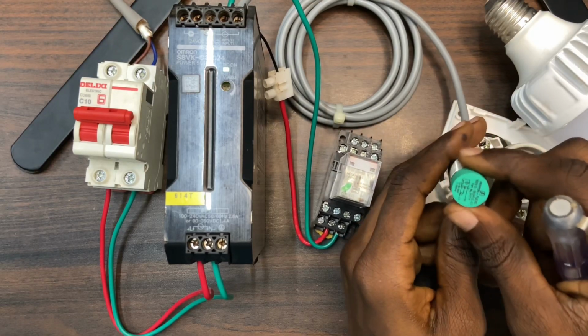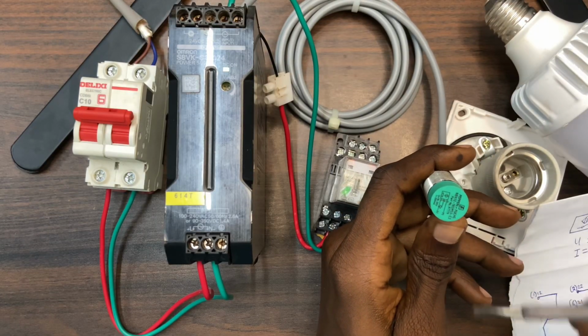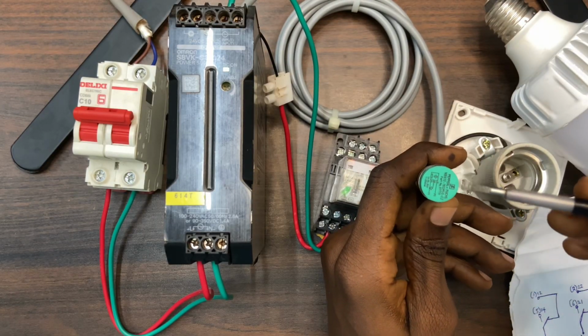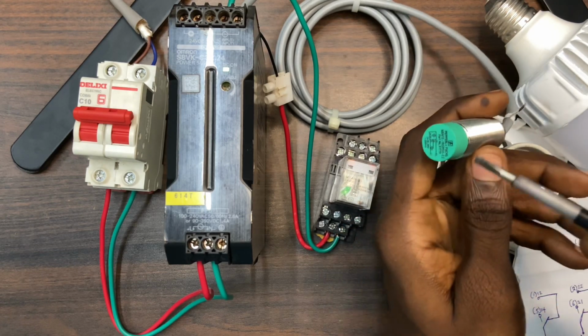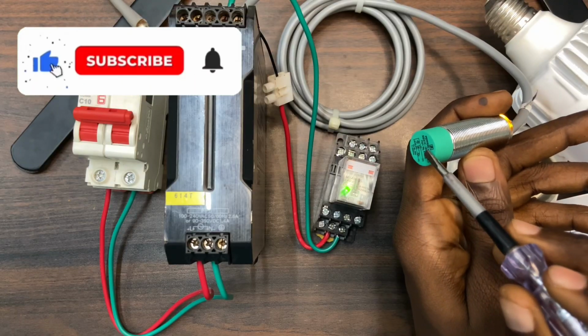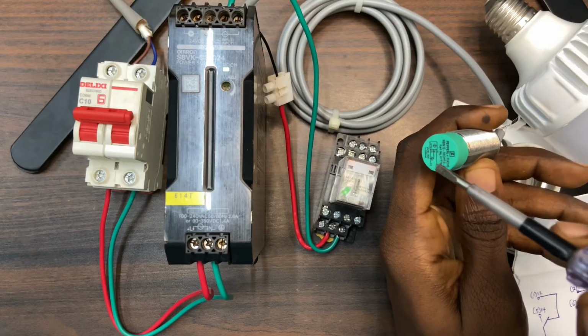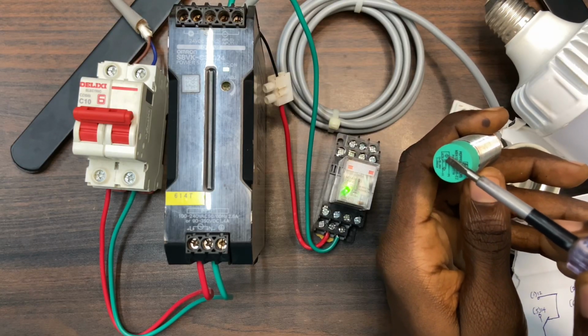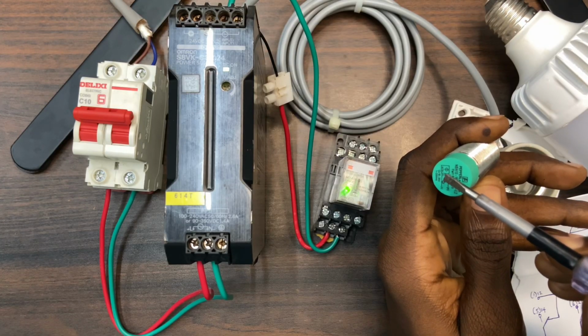And sometimes it depends on the sensing range. If the sensing range is very high, even if you bring the metal, something like this, it is going to work. But if it is low, unless you bring it very close to the sensor. So even if I touch the sensor with it, it is still going to work. And when I bring it upwards a little bit, it's still going to work.